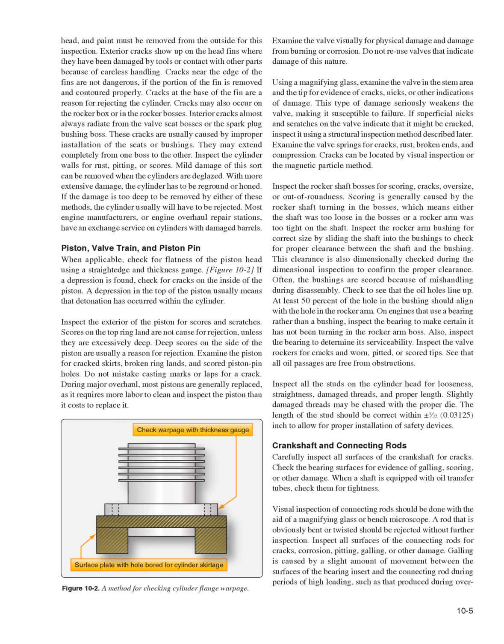Scores on the top ring land are not cause for rejection, unless they are excessively deep. Deep scores on the side of the piston are usually a reason for rejection. Examine the piston for cracked skirts, broken ring lands, and scored piston pin holes. Do not mistake casting marks or laps for a crack. During major overhaul, most pistons are generally replaced, as it requires more labor to clean and inspect the piston than it costs to replace it.